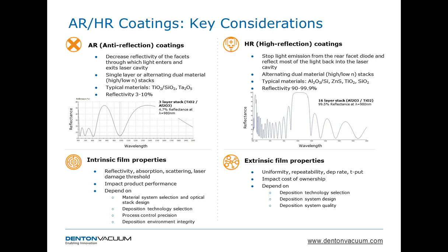They would depend on deposition technology selection, so what is the best quality you can achieve of the material for a particular technology. They also will be highly dependent, especially in the cases of a high number multi-layer stack, on the process control, precision, and also deposition environment integrity, such as how good is your vacuum, how clean is your system.